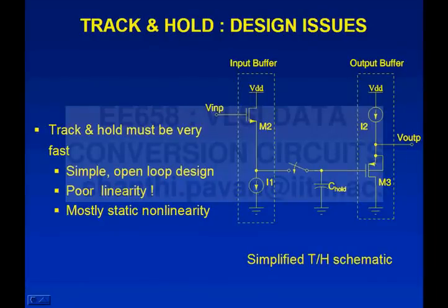For small signals, of course, the gain from here to here is some gm/(gm+gmb). In practice, all these are varying with signal, which basically means that the linearity of the small signal gain keeps changing depending on the value of the input. If the gain depends on the input, it is nothing but nonlinearity, so this causes distortion.